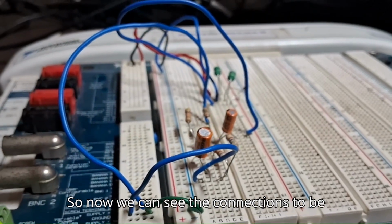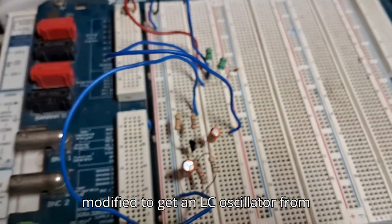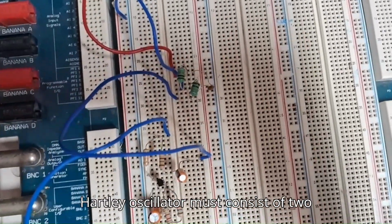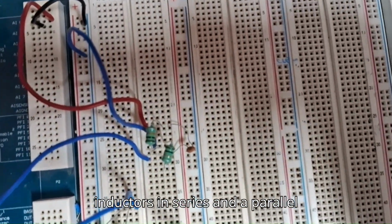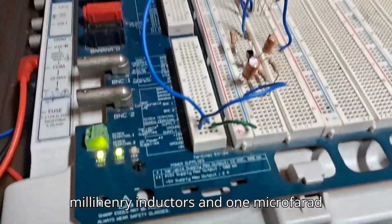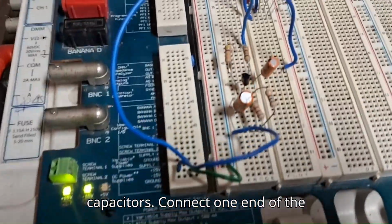So now we can see the connections to be modified to get an LC oscillator from the amplifier circuit. A Hartley oscillator must consist of 2 inductors in series and a parallel capacitor, called a tank circuit. The inductor values must be 1 millihenry and the capacitor 0.1 microfarad. In case this does not work, try 10 millihenry inductors and a 1 microfarad capacitor.